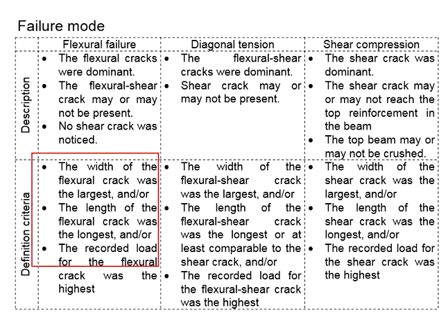These are the criteria to determine a flexural failure, where the width of the flexural crack is the largest as compared to the others, the length of the flexural crack is the longest, or the recorded load for the flexural crack is the highest.